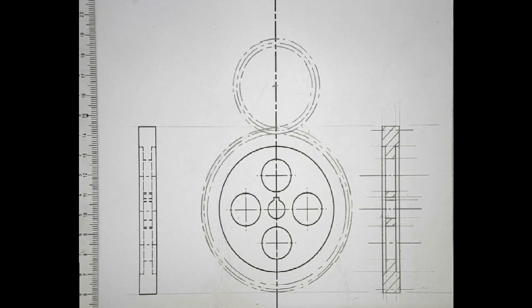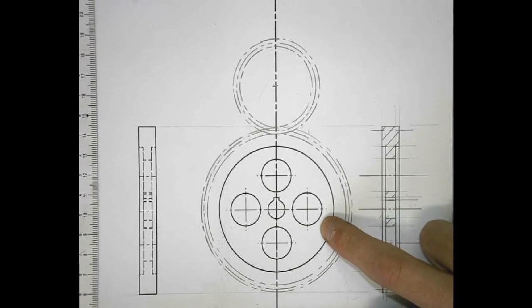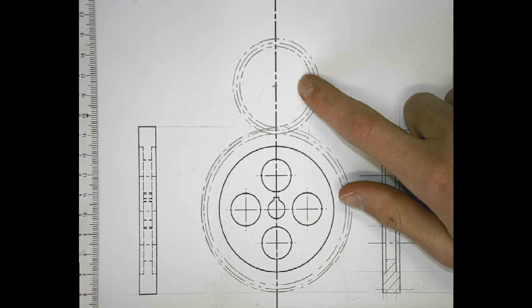With all of the relevant diameters for the gear teeth now represented, we will begin to draw the body of the gear in. Now, because the gear ratio is 2:1, it's safe to assume that anything that we measure off on our main gear will be half the size on our pinion.